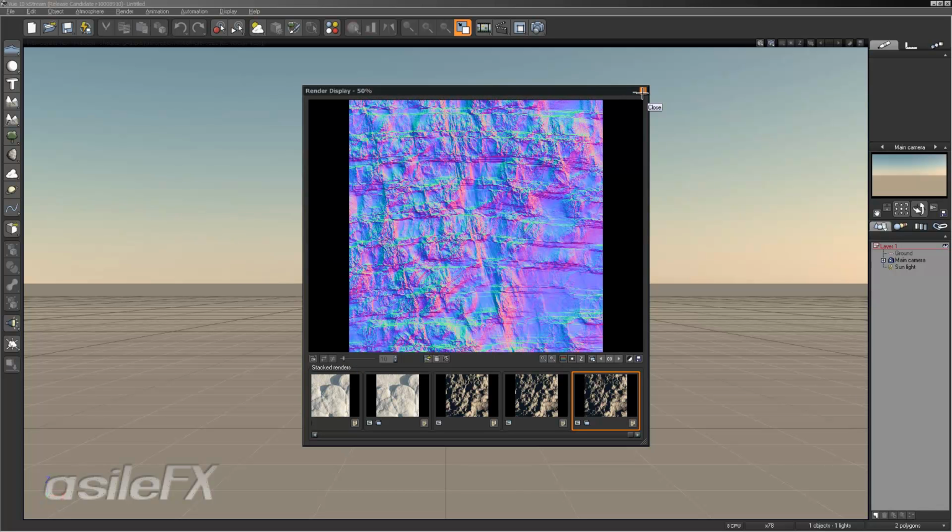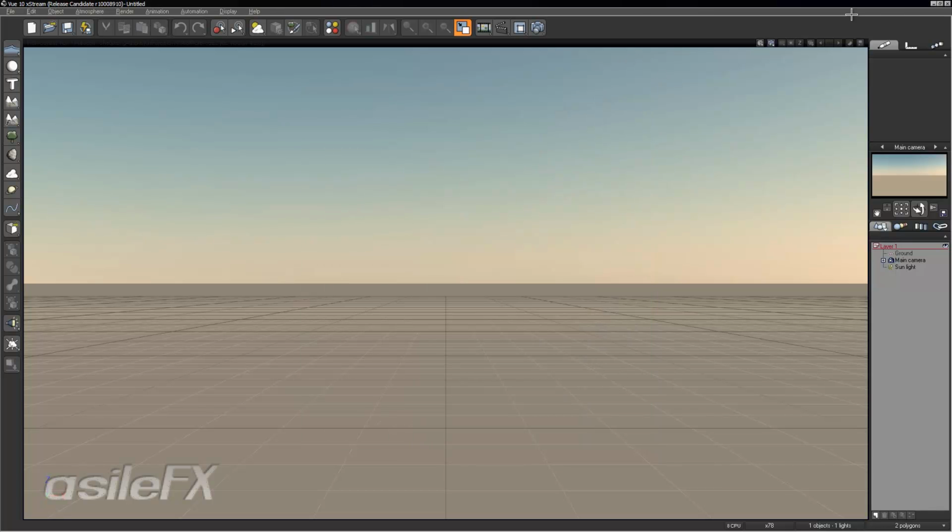It looks like sometimes there's something that interferes with the saving of the scene. Sometimes if you still have the scene open, it's happened to me a couple of times. So you should be able to just go to the render stack and keep that option on to save the render out just in case, or use a different format, maybe EXR format, 32-bit, and then downgrade it to 16-bit.